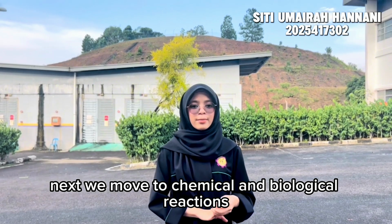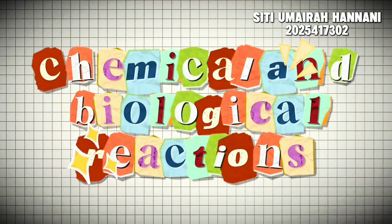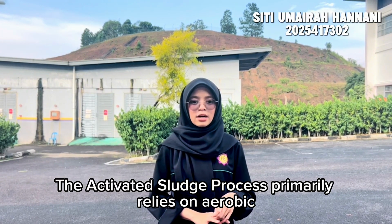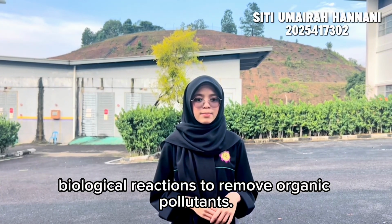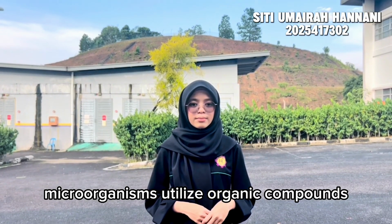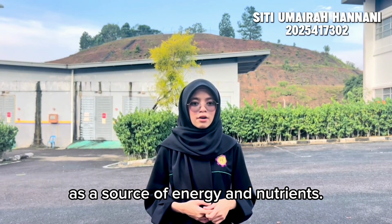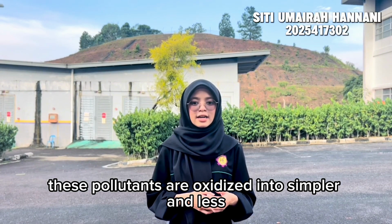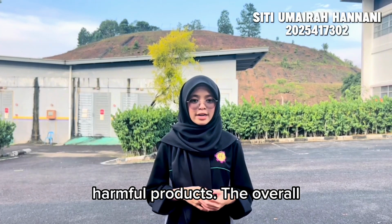Next, we move to chemical and biological reactions. The activated sludge process primarily relies on aerobic biological reactions to remove organic pollution. During treatment, microorganisms utilize organic compounds as a source of energy and nutrients. In the presence of dissolved oxygen, these pollutants are oxidized into simpler and less harmful products.